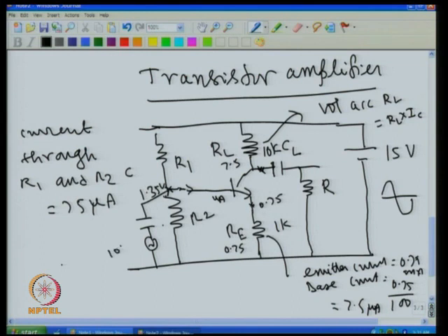Suppose I put 10 millivolt here, the same 10 millivolt, that is 7.5 plus this 10 millivolt comes here, and that produces AC variation across this, and the same variation is taking place here, and then you will get 10 times amplified voltage at this point. Now this type of amplifier is very popular, and all that you need to do is select these resistors correctly. For example, if we want a gain of 10, I put a ratio of 1:10, then you get amplified by a factor of 10.